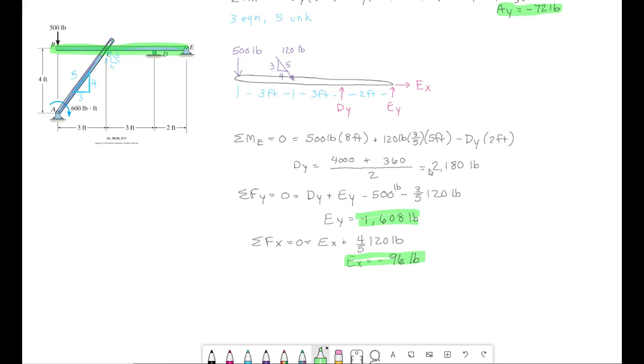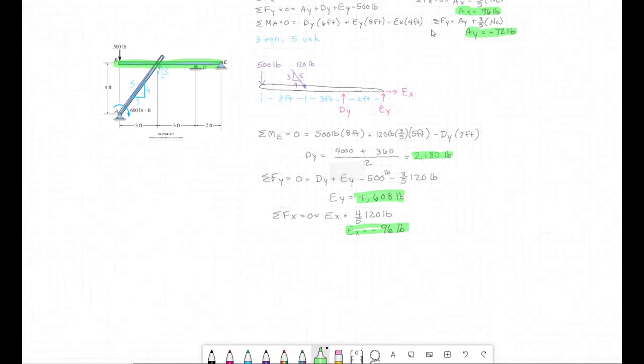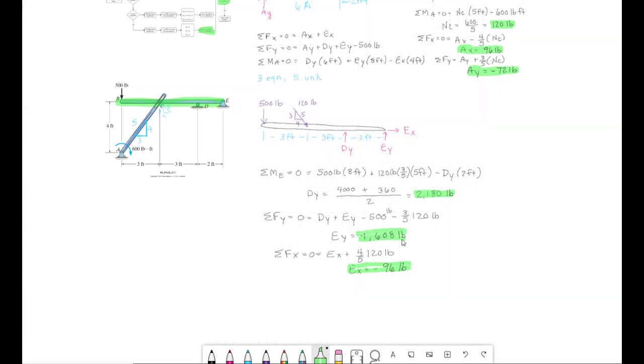So we've got 2 kips, 2,000 pounds pushing down here at D. E is holding back, so it's pulling it back down here at E, but it's also a little bit side to side, pushing out as this rotation here is trying to push through. But really, compared to the forces in C and A, D and E, those vertical forces at D and E are really significant, with this 500 pounds being a full 8 feet away from the pin end at E.